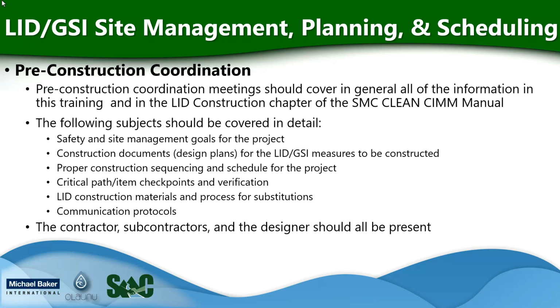The following subjects should be covered in detail: safety and site management, construction documents for the LID measures, essentially the design plans and what's expected in implementing those design plans, proper construction sequencing and the schedule for the project, critical path items, checkpoints, and verification, the LID construction materials and the process for evaluation and approval of those materials and any substitutions, and communication protocols. The contractor, subcontractors, and the designer should all be present at the pre-construction coordination meeting.